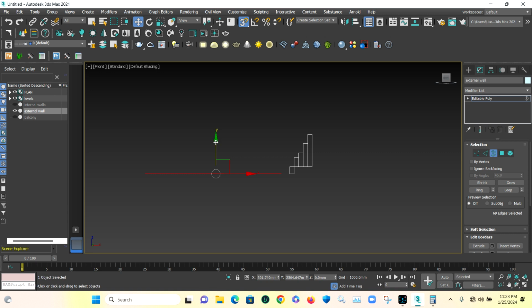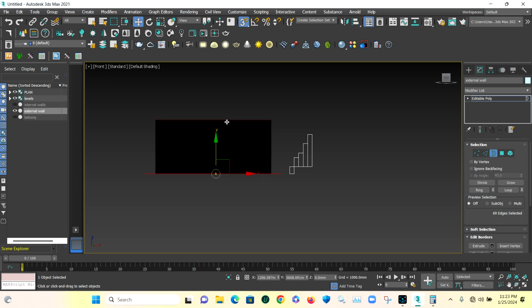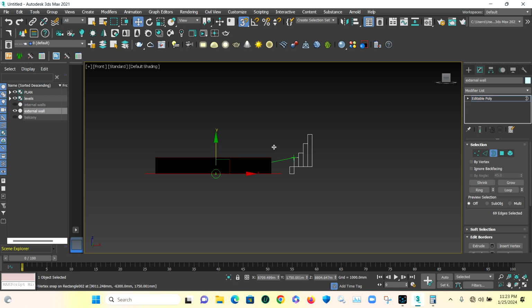We're just repeating the copy command now. Hold shift, place your cursor on the Y axis, left click, hold and drag. You see this thing is following me now, it's going with me. So anywhere I release my left click, it will stop there. Remember, hold your shift key, don't leave it. So first of all, I'll drop it to this level. This is the DPC level.